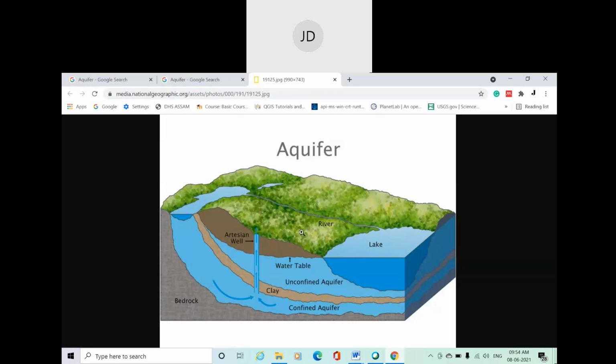A shallow tubewell is inserted where? Inserted into the unconfined aquifer. Shallow, the particular hand pump, you can see, the hand water pump, is inserted into the unconfined aquifer, which is located at a shallow depth nearby the ground. But boring is done to a deeper depth of the ground, right? So it basically targets the confined aquifer where the water is stored. The water can be stored for years and years. And storing the water in a confined aquifer takes a long time, 100 years or so.